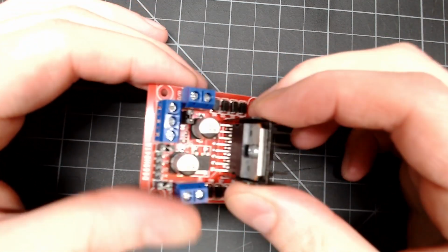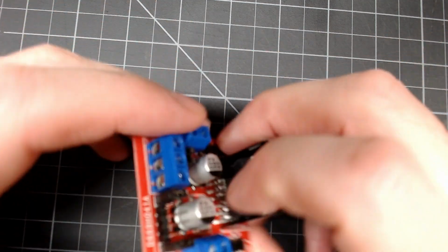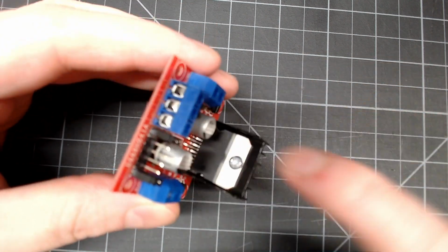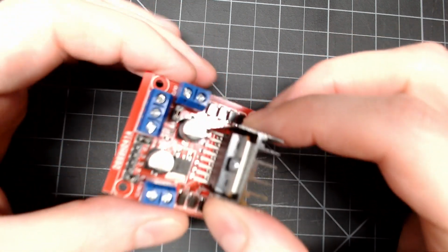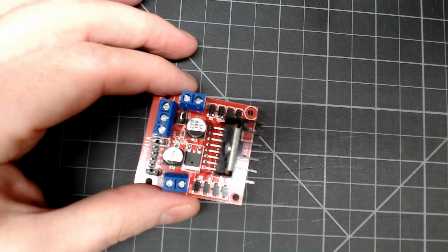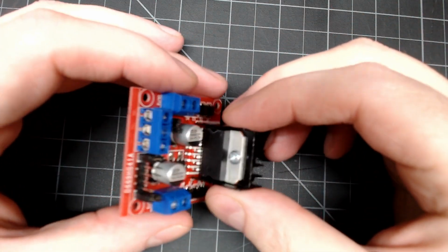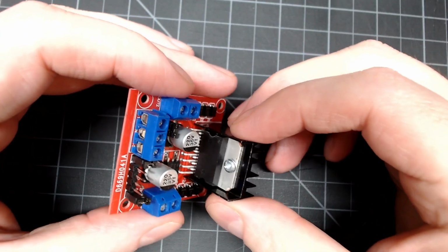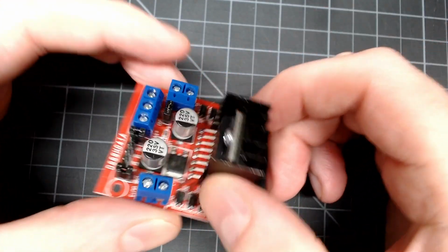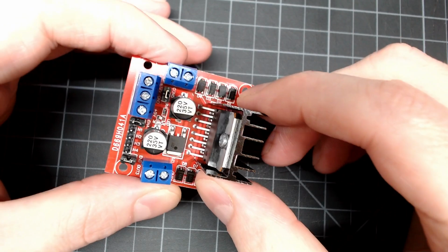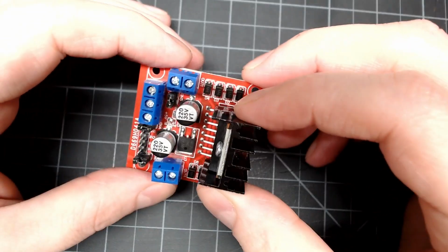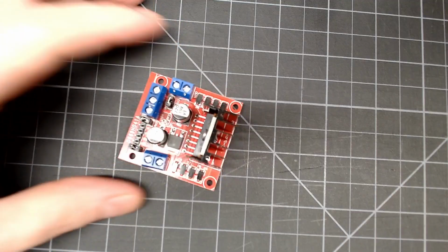Now, you can build this yourself, and it's a reasonable way to do it, but you can also get something like this. This is an H-bridge. That's all this is. The transistors, the MOSFETs, are in this chip, and for a decently powered motor where you want to crank a lot of power into it, those MOSFETs are going to pull a lot of energy. And so that's why it has a heat sink on it. So the MOSFETs are all in here, and they have this heat sink here, and we can see the various different pieces. And that's it.